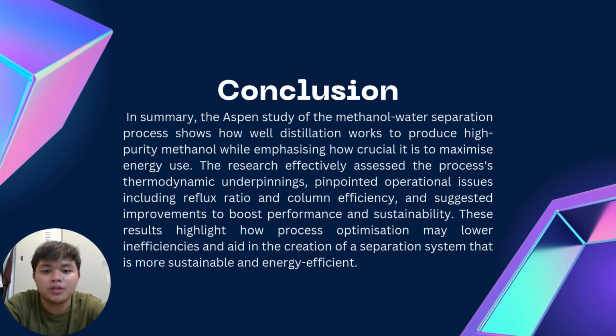So this is our conclusion, answering our objectives. In summary, the Aspen study of the methanol water separation process shows how well distillation works to produce high purity methanol while emphasizing how crucial it is to maximize energy use. The research effectively assessed the process thermodynamic underpinnings, pinpointed operational issues, including reflux ratio and column efficiency, and suggested improvements to boost performance and sustainability.